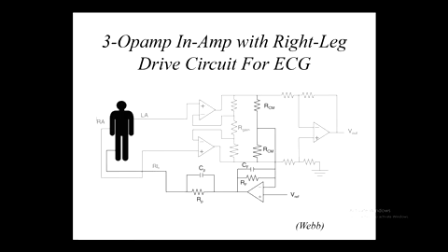We're running out of time. Here's where the alternative to the guard circuit is presented, and we actually have the common mode signal now derived from the same place as before, and once again we could have taken it from a tapping point halfway through the gain setting resistor.